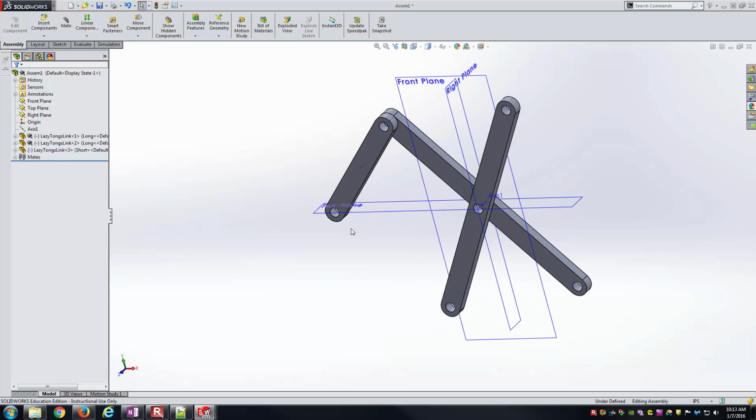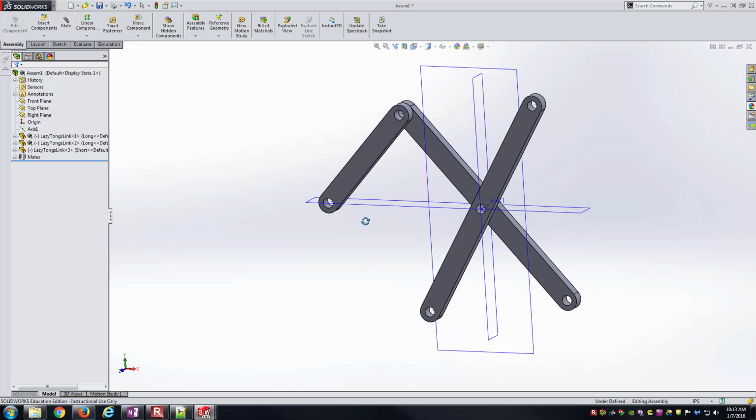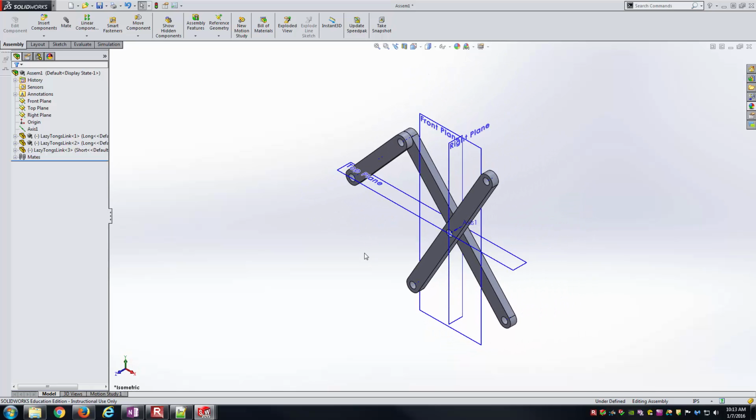You can always play around with it, and I would encourage you to actually play around with the model before you get it complete. It's one of those things you don't want to have built the entire mechanism and then have it not function. And so I would strongly suggest, as you put in a couple of components there, that you grab a hold of some stuff and see if it's working the way you want it to. Because I'll say this probably more than once in this video, if it's not working correctly in this model tab, it's not going to be working correctly in the motion study tab there. And so it's much easier to figure things out in the model and then have things run a little bit smoother in motion, as opposed to having compounding problems basically then inside of the motion study.